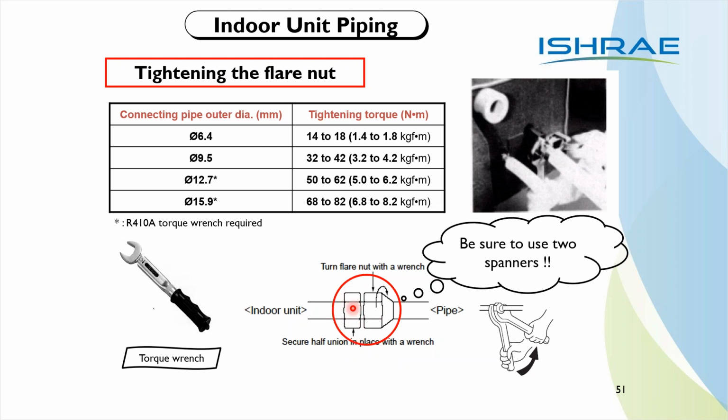Never hold cutting pliers. Never use a pipe wrench. Never use grip pliers. I know a lot of people use this practice at the site because you may not have the spanner, but that is not the right way. Get the right spanner, get the right tools to work so that your work becomes easy and you do a good professional job.